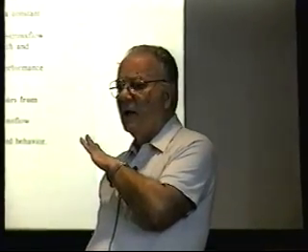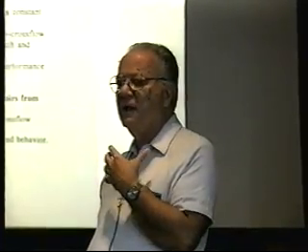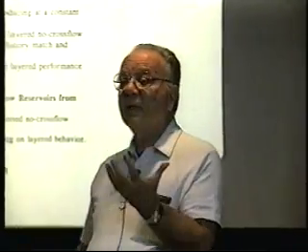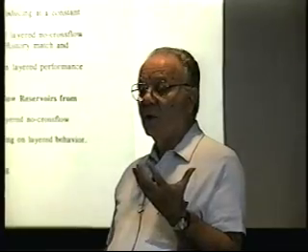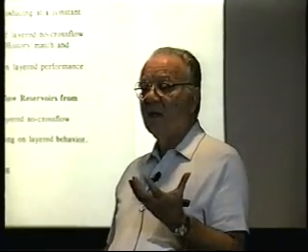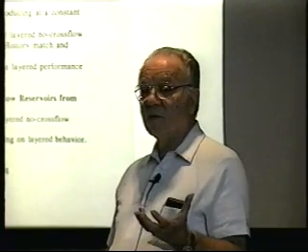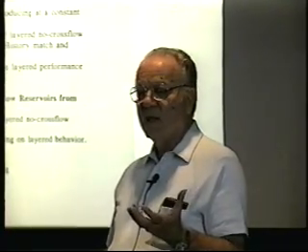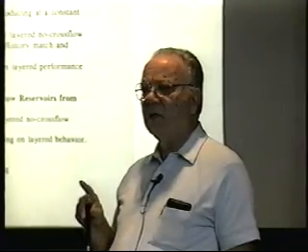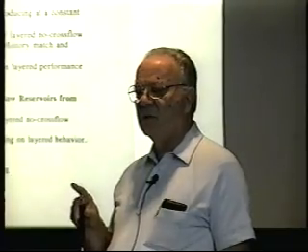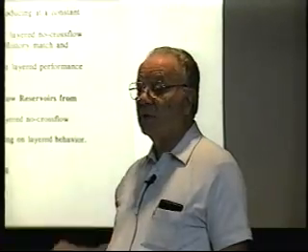There's been a lot of emphasis over the years on pressure transient analysis, but the only application of the numbers that you get is to make a production forecast, or to analyze the data in terms of whether these wells need stimulation, and whether I can increase the production rates as a function of time. So this is what it's all about. You really will never realize the impact of the data that you're getting from the pressure transient until you take that data and make a production forecast.